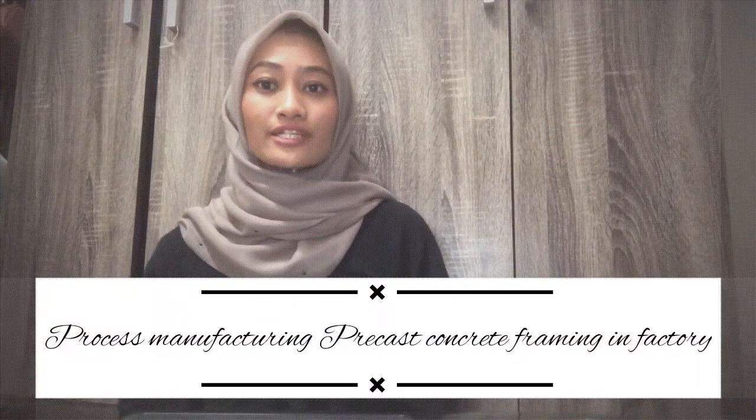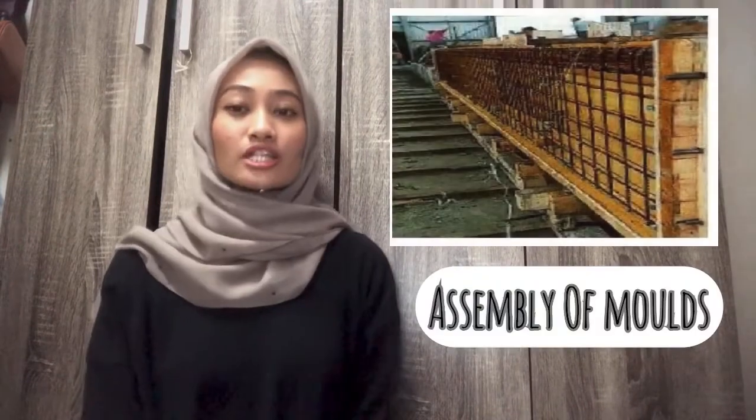Next, I will proceed to the process of manufacturing precast concrete framing in the factory. First, as we can see from the picture, is the production of the reinforced cage and main connection. The precast factory often has a specialist workshop for the manufacture and maintenance of molds. Next is the assembly of the mold.